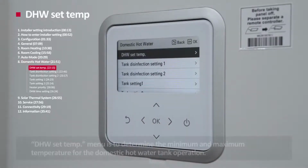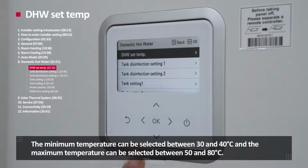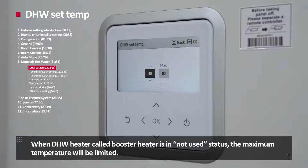DHW set temperature. DHW set temperature menu is to determine the minimum and maximum temperature for the domestic hot water tank operation. The minimum temperature can be selected between 30 and 40 degrees Celsius, and the maximum temperature can be selected between 50 and 80 degrees Celsius. When DHW heater, called booster heater, is in not use status, the maximum temperature will be limited.